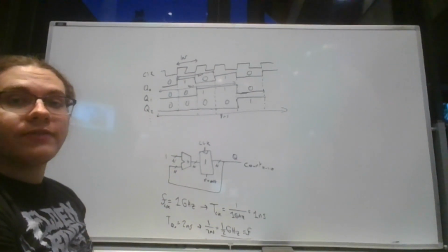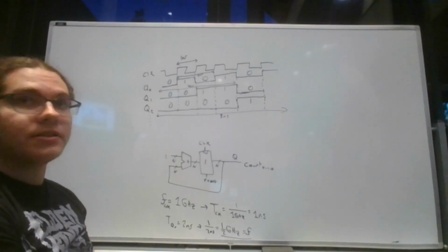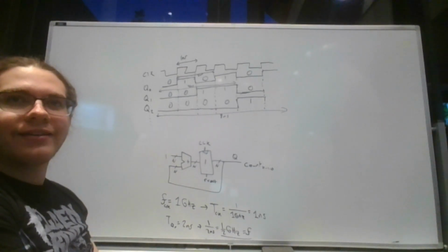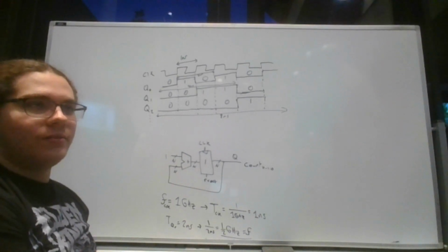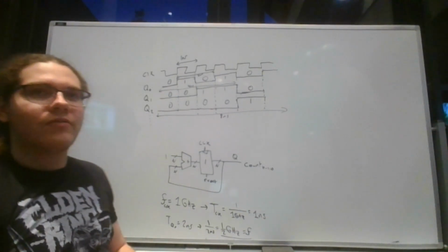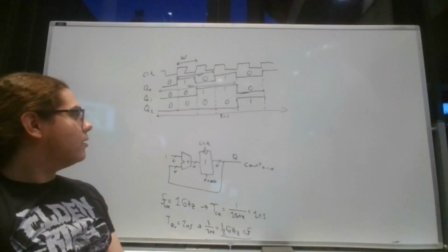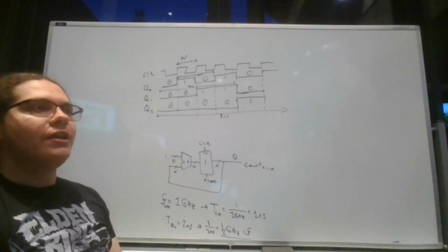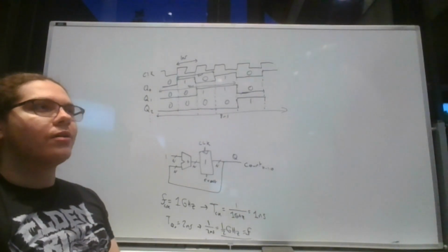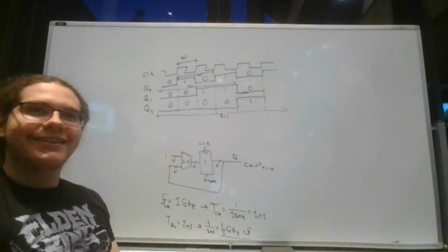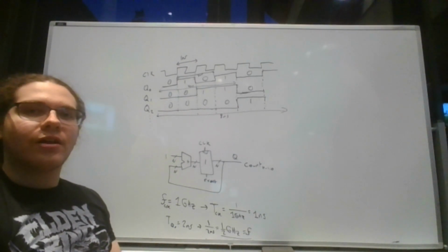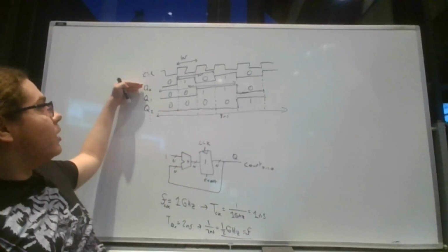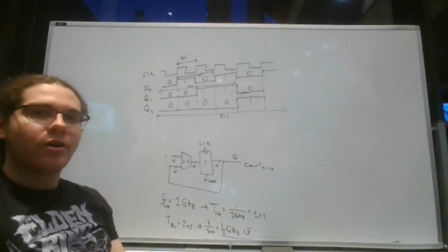And so now I can develop an arbitrarily slow clock, as slow as I want to go. I don't have to go down to just 1 hertz. I can go slower than that. I can make it so it's in millihertz or something stupid. Something very, very slow. This is very helpful if you want to, for example, read the inputs from a water bottle to measure its water level. This is how you generate that slower clock. And then you can pick your bit depending on how slow you want to go.